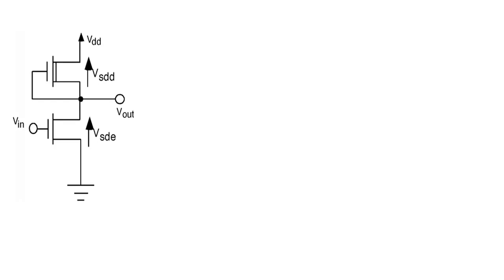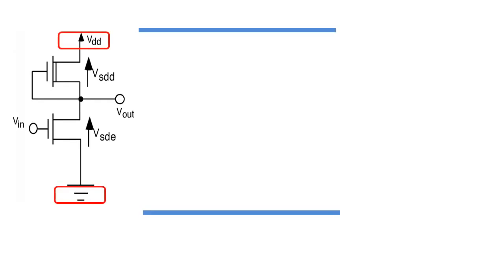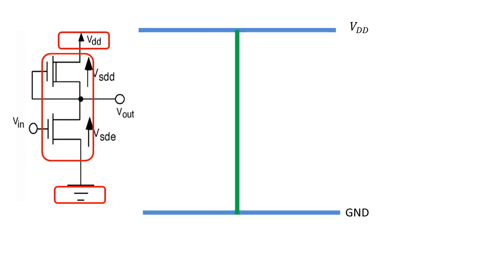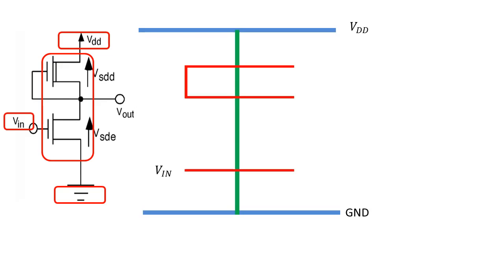We begin with drawing the VDD and ground connections for the depletion MOSFET. Since these are metal connections, we represent them by blue lines. Next are the two NMOS. Since the NMOS have an N-type substrate, it is represented by a green color. Next we move on to the inputs. The depletion MOSFET has an input which is directly shorted with the output, and the other input is Vin.